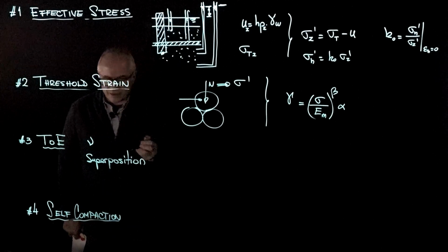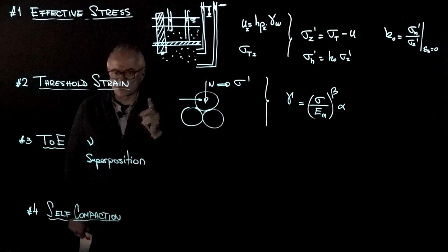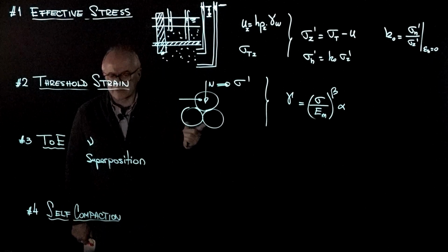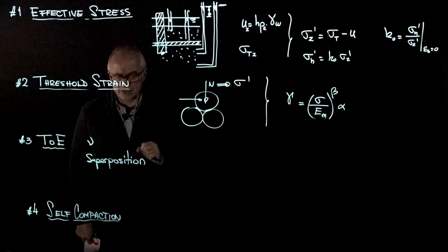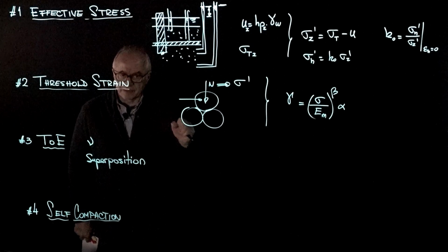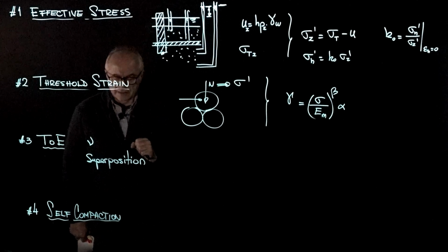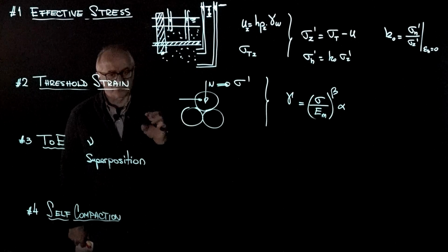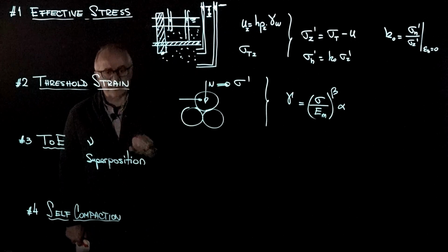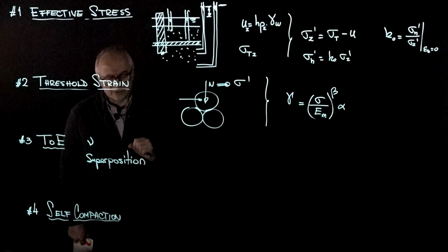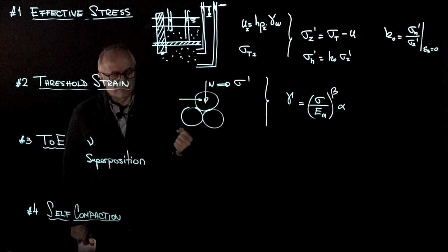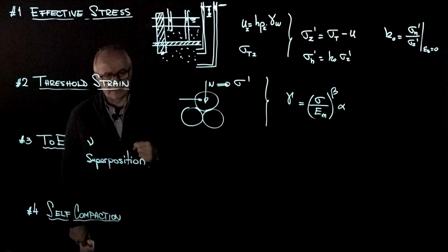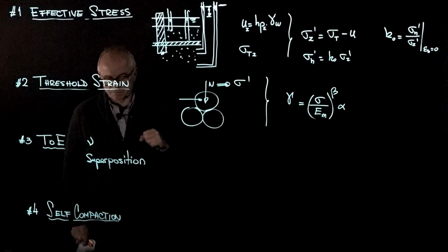But the other question related to theory of elasticity was to demonstrate the shear modulus as a function of Young's modulus and Poisson's ratio, which we did previously. Please do it step by yourselves, because it will also give you insight and force you to refresh the concept of stress and strain tensors, which we're going to do in the form of Mohr circles for stress and Mohr circles for strains, and to understand the important difference between the mechanics shear strain and the engineering shear strain.